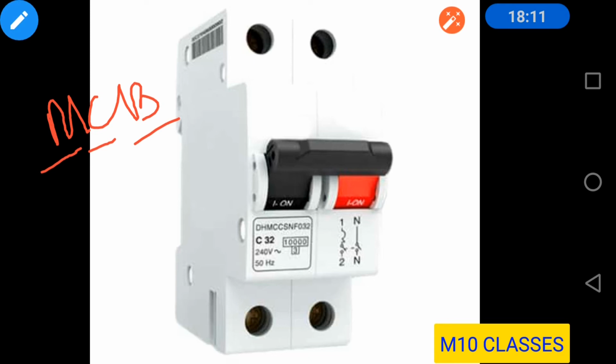Now what is the rating here? You can see here this C32. This C32 means it has the current rating of 32 ampere.